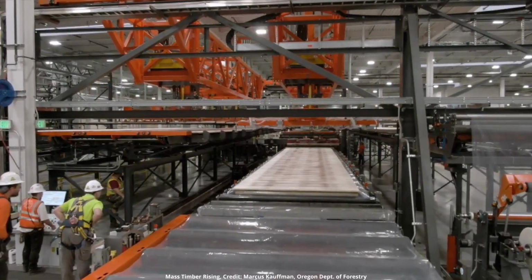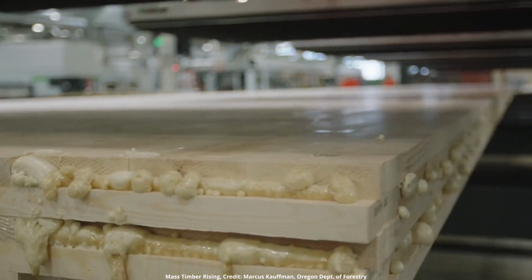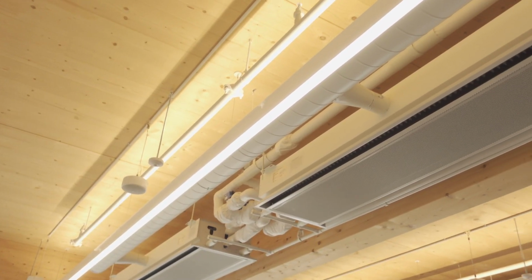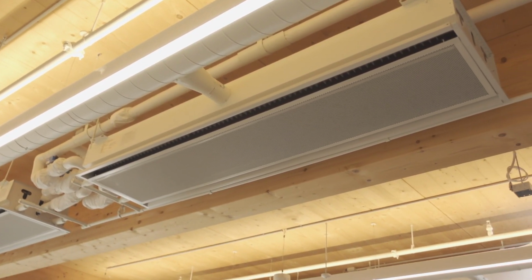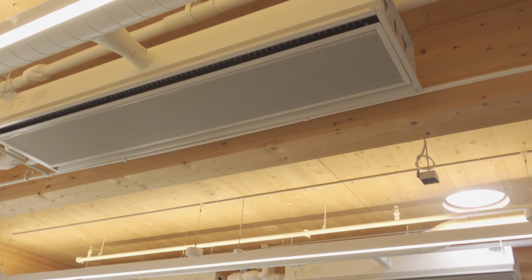Now, you're still going to get a benefit in terms of the overall cost when compared to, say, the full panel with all laminations of the same thickness, because you are reducing the volume, but it may not be a linear relationship. So understanding those nuances of fabrication and manufacturing costs and how they lead into unit cost is important in terms of how you go about making those design decisions. So I hope some of these tips have been helpful to you in evaluating, is your design for your mass timber project the most efficient that it can be?